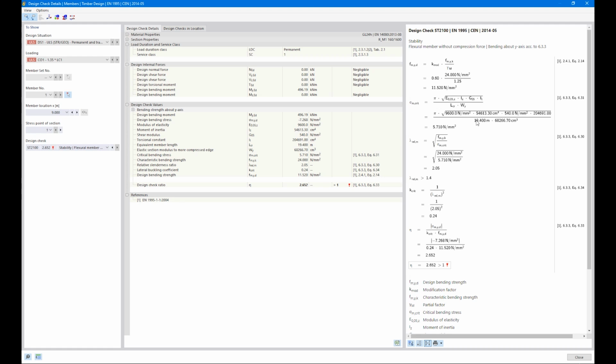So we have 18 meters beam length multiplied by 0.9 was 16.2 plus, since the load is applied on the top side, plus 2 times 1.6 meters equals 19.4 meters. We calculate the slenderness again, and due to the approach of the Eurocode, we will get this reduction factor. So we modify our stress design check, in this case the 63, we multiply it by 0.63.